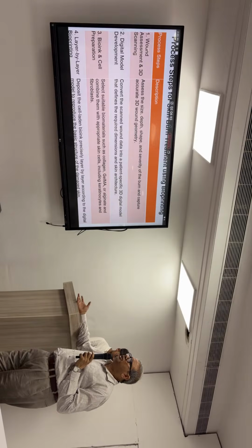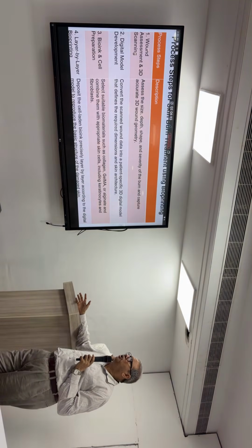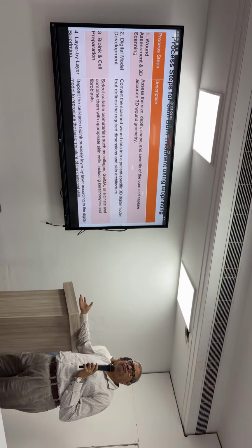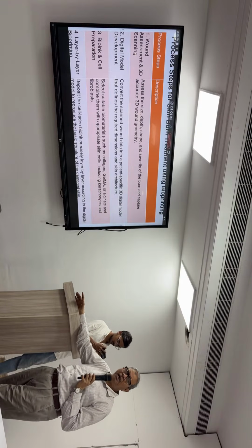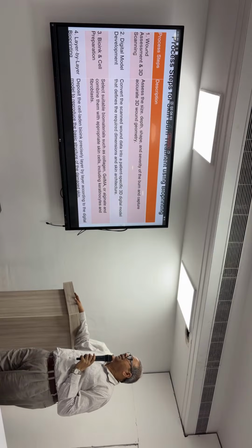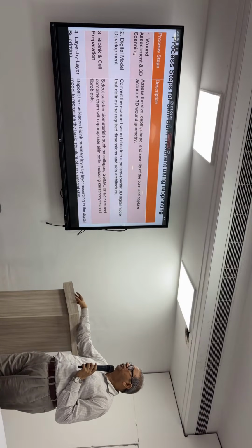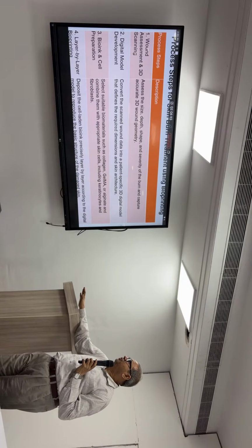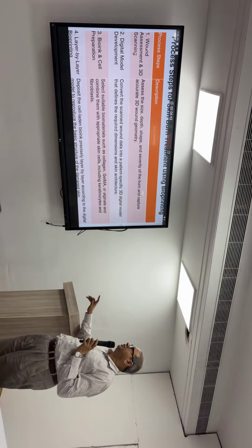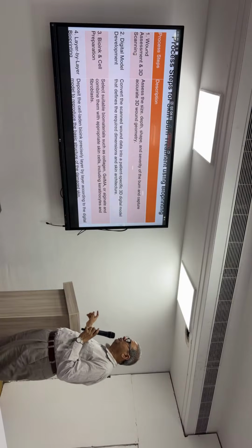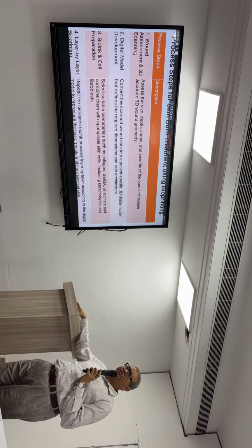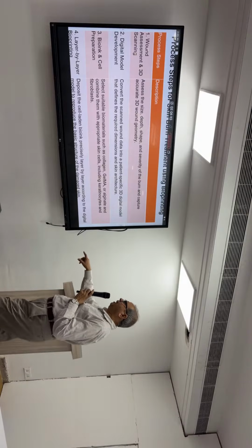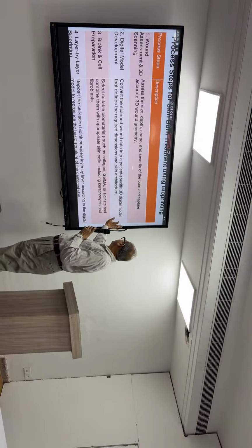We assess the wound, and after that you scan through 3D scanners. 3D scanners are again which are used for the ordinary additive manufacturing platforms. And then what we do is that from the scanned wound data, we make a patient-specific 3D digital model. And from that model, we make a scaffold, and then bio ink and cell preparation is done, and then layer by layer printing is done precisely.